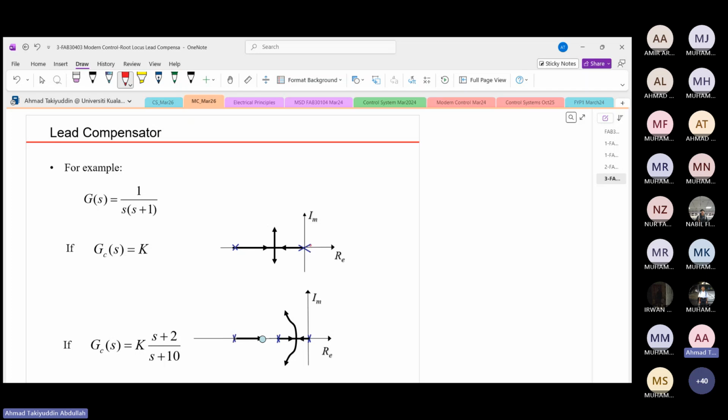When you consider the plot with the starting and ending points, the poles are normally at k equal 0. As you need the root locus representation between 0 and infinity, this vertical line will show where you have k equal infinity.